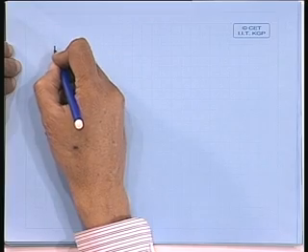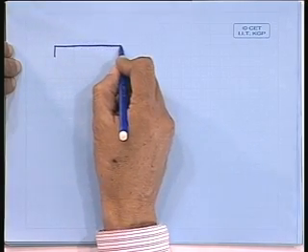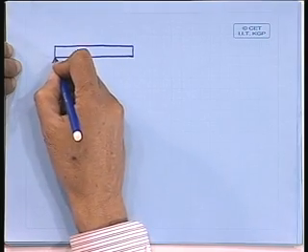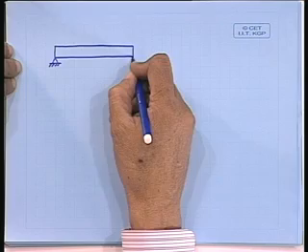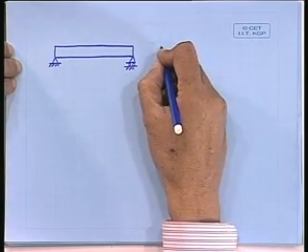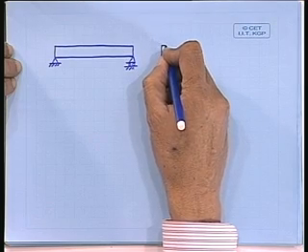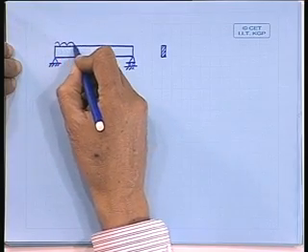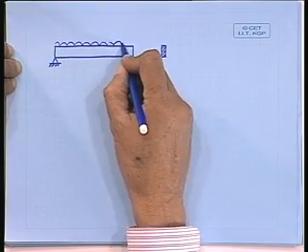So if you consider that the material is linearly elastic, fully plastic, then let us try to examine a very simple beam and see how it works in that condition. So I take a beam, a simply supported beam, and that beam is also very simple. That means the cross section I am assuming is just a rectangle, and I also assume some uniformly distributed load.